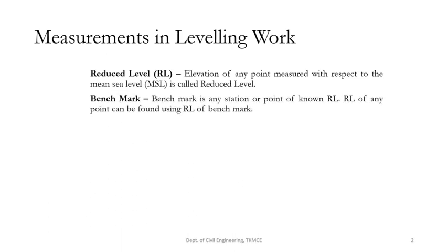And the term benchmark means any station or point of known RL. That is, the elevation of that point will be known to you. RL of any point can be found using the RL of a benchmark. Suppose when you are traveling in a hilly station, you could see the markings on the side of the road saying this point is at a height of, say, 1000 meters above the mean sea level, which means the particular point situated at that marking is at a height of 1000 meters from the mean sea level.